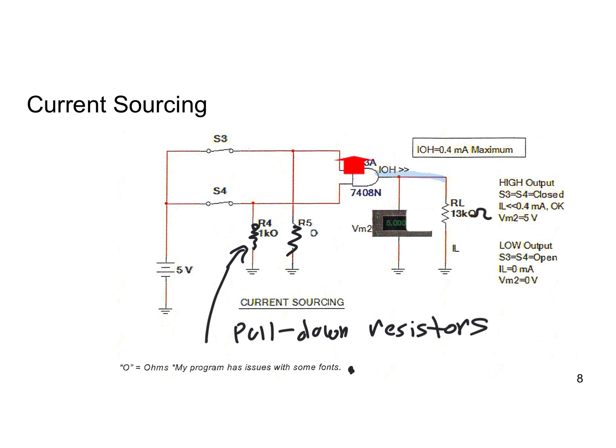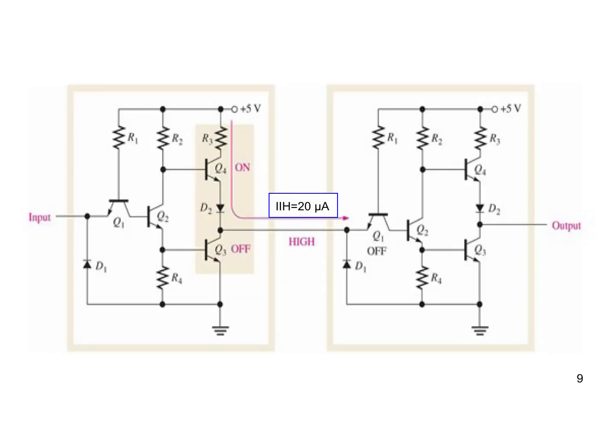Current output high is 0.4 milliamps maximum, and we saw that from the data sheet. This is why when you're using an LED, you either have to go current sinking, or you have to use a transistor interface, or go to a different logic family. They may have more current capacity, and you may be able to directly drive it. With the LS series, you cannot.